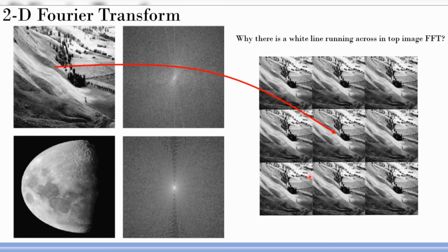Now if you see, there is an issue, right? Just see the Fourier transform at the edges of the image. In this case, for example, you see there is a dark shade here and a bright shade here, so it appears like there is a sudden transition, and any sudden transition in an image will look like an edge. There is a very high sudden transition, particularly in the row direction. Okay, so which direction is this for us? This is the y direction.